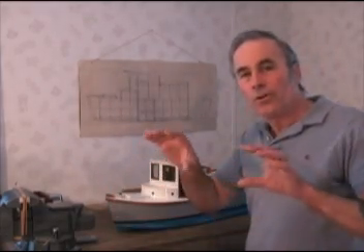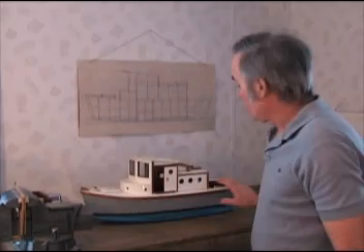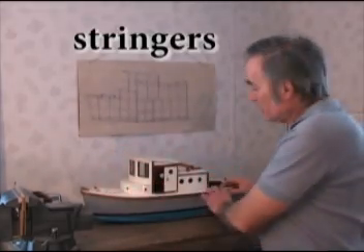Now, it's up to the individual builder whether up is up when you're standing there with the boat upside down, or up with regards to the boat. With the boat upside down, my arrows will point to the ceiling because that's up to me. And as long as you're consistent, it doesn't matter. That way, when you make a piece, you know exactly where it goes and how it sits on the boat, which side it goes on. It's just a way of marking your pieces so they go back the way that you fitted them.